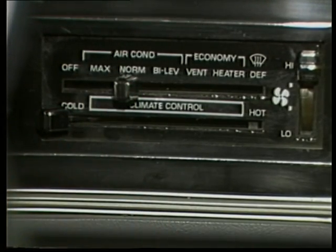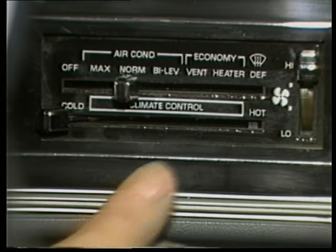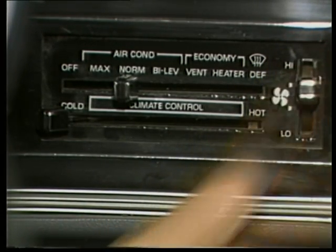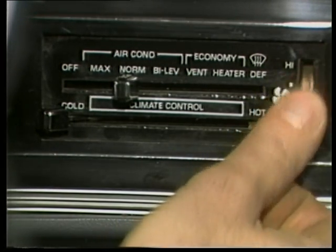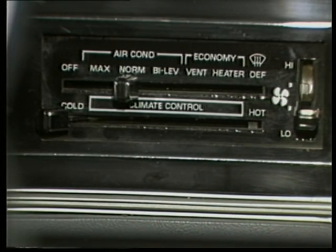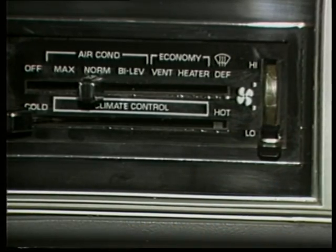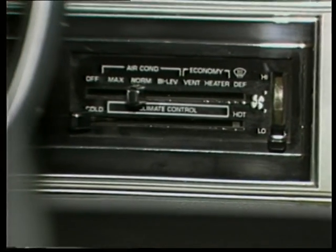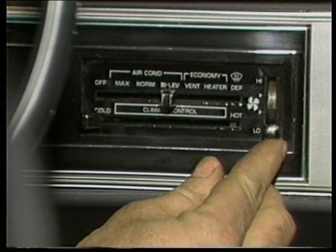Then, move the mode lever to normal and check general output. Move the fan switch to each speed to check blower action. This checks the blower motor, switch, and dropping resistors for trouble. Move the lever to the bi-level position. You should then feel air blowing out of the dash vents and out of the floor vents.